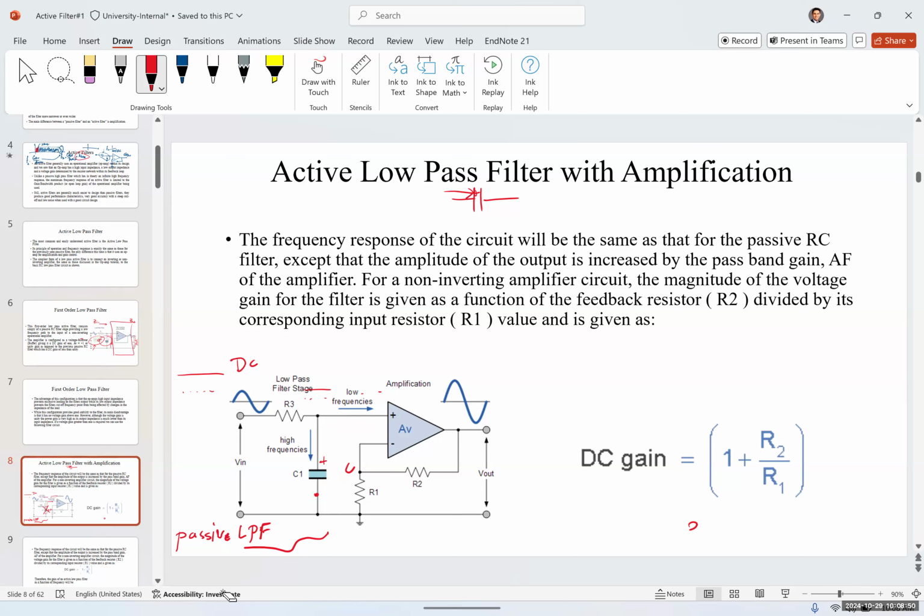But if we have a large enough frequency, a high frequency, at one point it's going to overcome the impedance of the capacitor. That high frequency is going to pass through this capacitor, yes? It's going to jump through the capacitor. And now what happens to the capacitor? The capacitor becomes a short circuit. So now the input has been shorted.